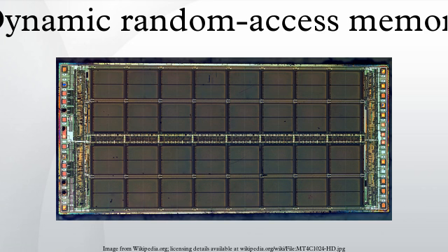This memory was primarily used in graphic cards with Tseng Labs ET6x00 chipsets, and was made by MoSys. Boards based upon this chipset often use the unusual RAM size configuration of 2.25 megabytes, owing to MDRAM's ability to be implemented in various sizes more easily. The size of 2.25 megabytes allowed 24-bit color at a resolution of 1024x768, a very popular display setting in the card's time.